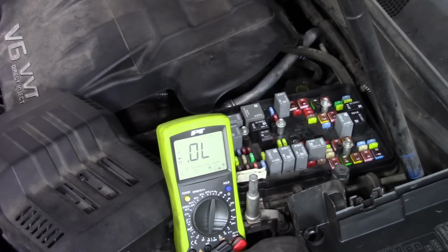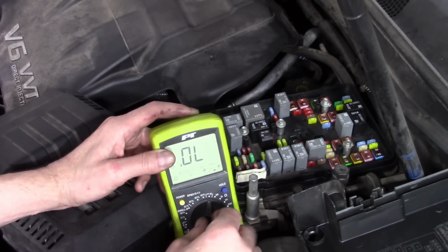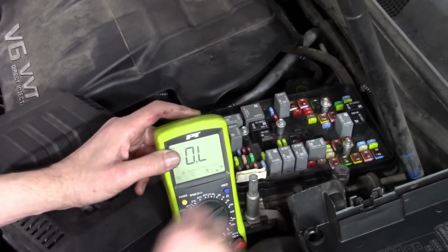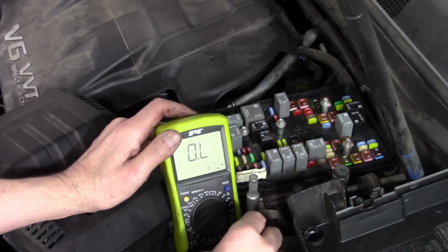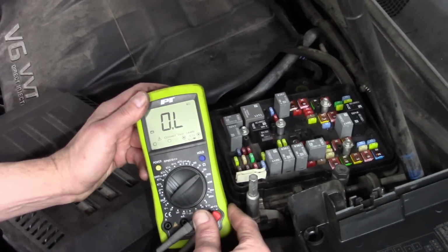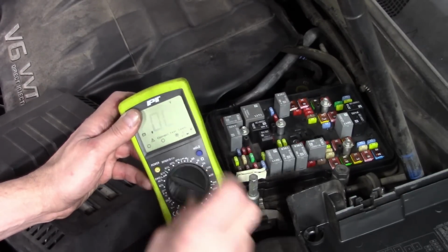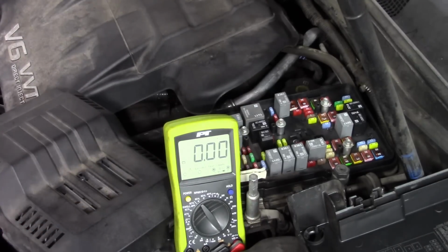Okay, for what we're going to do now, I think we'll start off using the DVOM. We're going to be looking for voltages now. So what I'm going to do is, and there's different ways we could do this. Of course, we could look at continuities through a ground or something. I think this will be the easiest way. Again, we need to just identify these terminals. I don't think it matters how we do it, right? As long as we identify them. So I'm going to go to a 20 volt scale there. I'm going to look for voltages here.